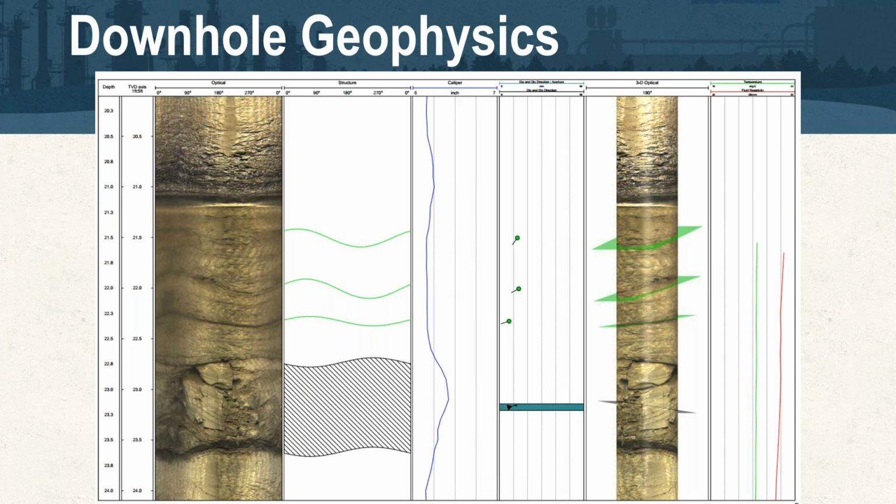The liners tend to be a bit less expensive, but they're a little harder to move in and out because they have to be reeled up. The Westbay, the Waterloo, some of the Solinst systems, that's a lot of pipe. Those are actual packers in some of those cases, so you've got to inflate those and seal off those zones. That can be tricky to handle.